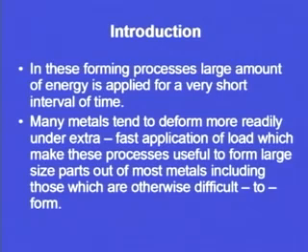In case of deep drawing, if we take the example, we are using a punch and a die type of arrangement, and the punch goes into the die and in between is the sheet metal which we want to deform. So, the process is not sudden, it is not impact loading. If we give impact loading, then there are chances that the sheet metal may fail. The cracks may appear, some micro cracks may appear, and that may further result into a catastrophic failure.